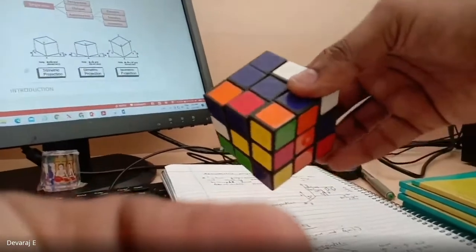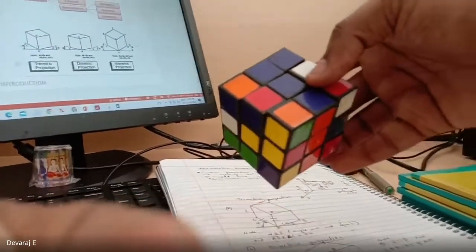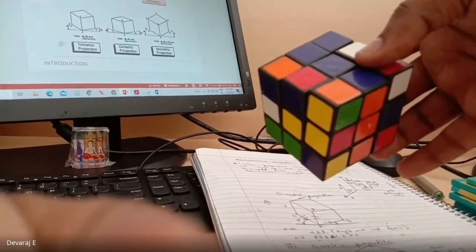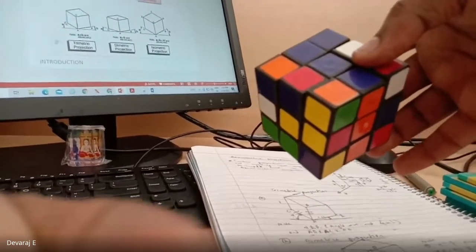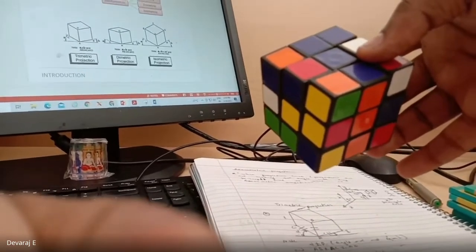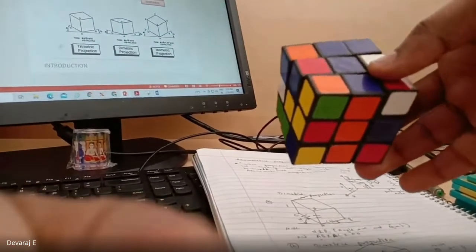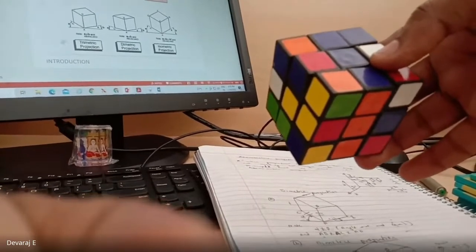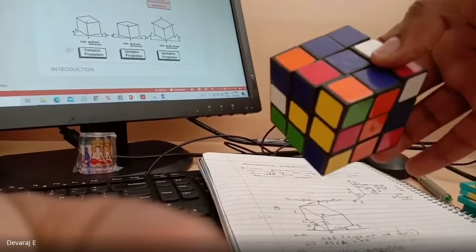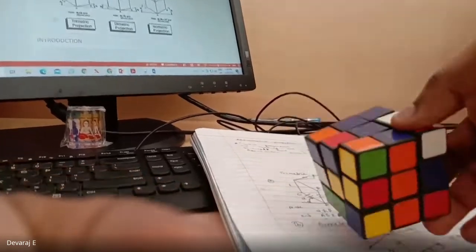So when you see the dimetric, alpha will be equal to beta, AB will be equal to AC, but not equal to AD. But when you see the trimetric, alpha will not be equal to beta, the angle changes, as well as AB will not be equal to AC, and AC will not be equal to AD. Right? Okay, thank you, sir. So anyone has any doubt?